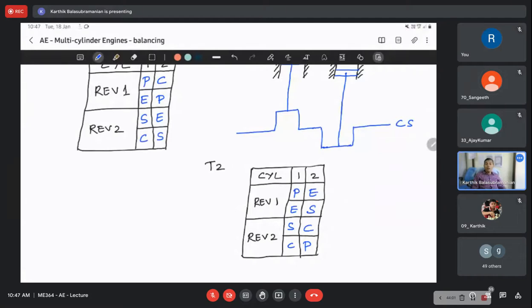It's the same crankshaft. So now, let's say a 1000cc engine. I can go with 1 cylinder of 1000cc capacity, or 2 cylinders with 500cc each, or 4 cylinders with 250cc each. Which is better? Sir, 4 cylinders with 250cc each. Obviously, 4 cylinders with 250cc each, because you will have more uniform distribution of power and there will be power overlap. Though power from each cylinder will be smaller compared to a single cylinder, you have power overlap, which gives you smoother rotation of the crankshaft. So that is what I meant by power overlap.